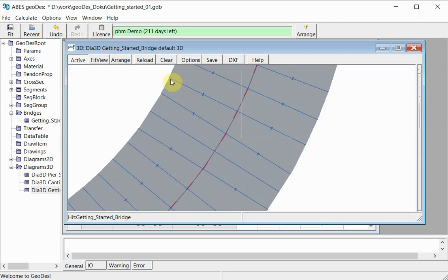And also the program knows that if we cast this, there will be a bulkhead on this side, and the sides here and here will need to be perpendicular to this bulkhead. So therefore this geometry of this segment is set out to bring it back to the axis, the segment center line, and also to make sure this segment can be cast in a rectangular casting cell.